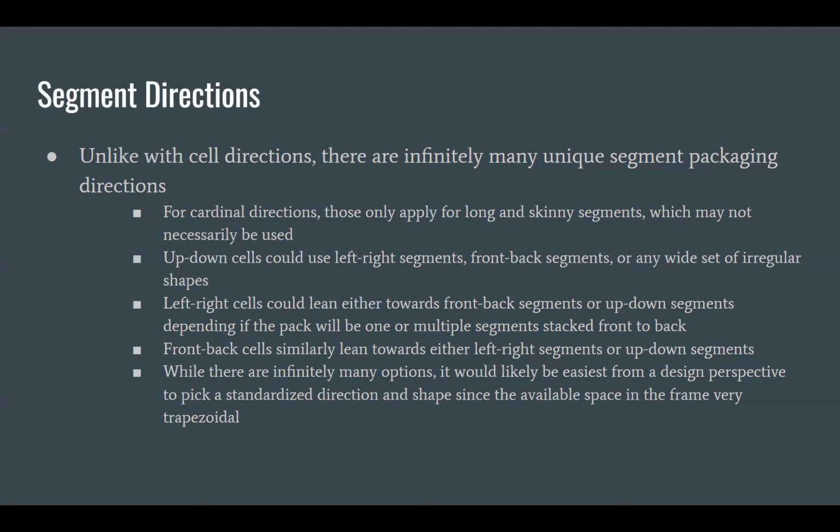For example, we have 4 cells in parallel. They recommend putting the 4 in parallel in the same segment together rather than splitting them 2 and 2. When you split it up like that, you get higher voltages between your segments, but now you need to track twice as many independent cell voltages because these ones could fluctuate differently than those ones. You don't have to, but it's strongly recommended.